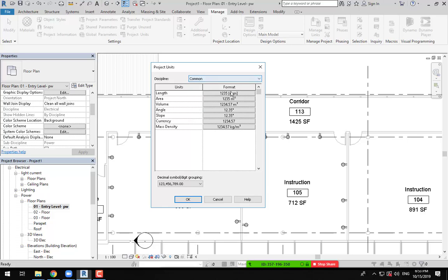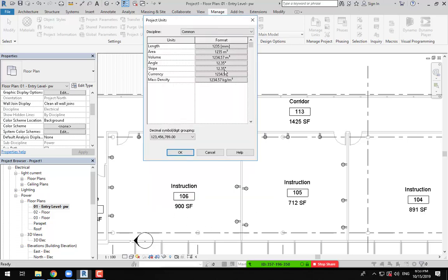But there is something very important here. These units belong to our project. Already area here is square meter, but rooms are related to what? They are related to the architect model. The architect model units are British units, square feet. So if you need to change these units, you need to change them from where? From the architect model. Understand this? Okay, we will do it later, no problem.